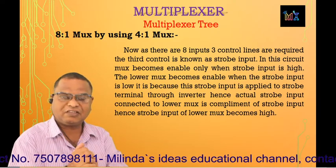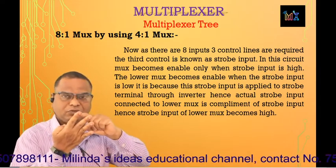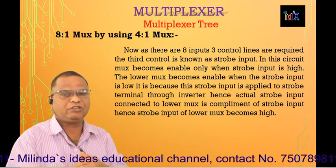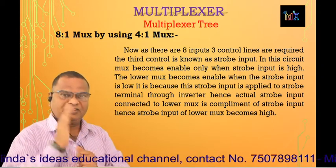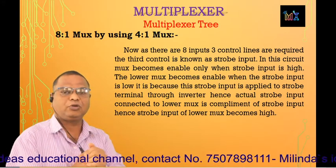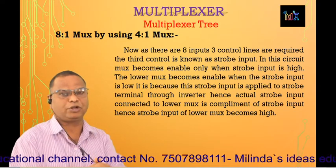That means in this case the output Y1 is equal to either D4, D5, D6 or D7, and that data is connected to the OR gate and then to the output terminal. So the strobe input, in this case S2, decides which mux is in enable mode, and the remaining control inputs decide which data is selected and fed to the output terminal.